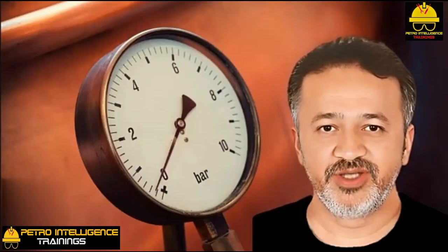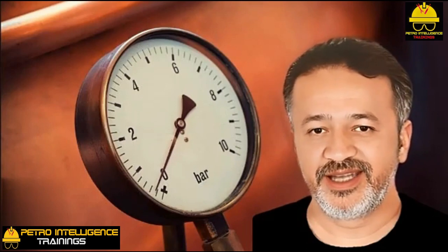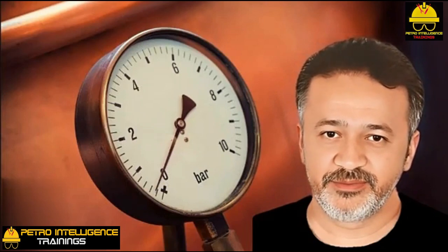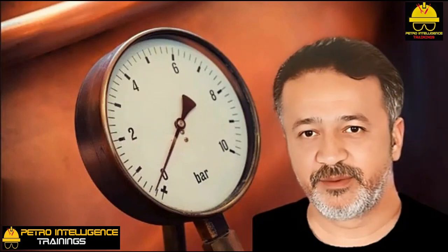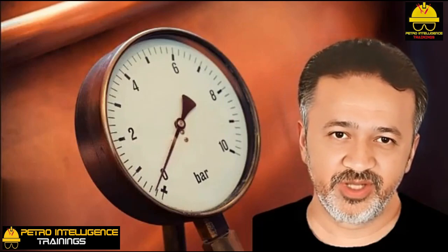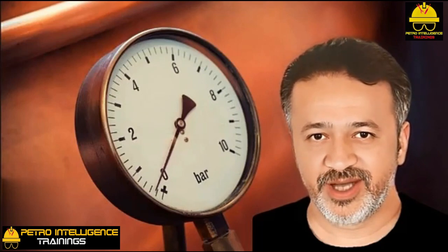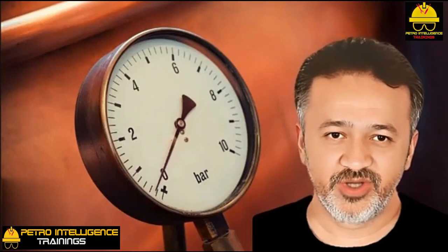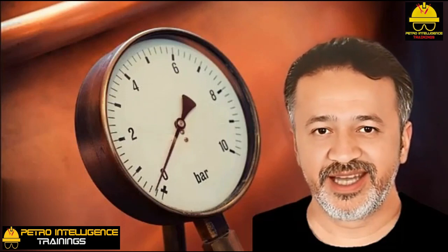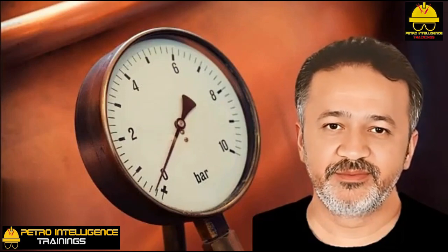Pressure point location. Locating a pressure tap in an area of high velocity is likely to produce a lower pressure indication than the real flowing pressure. Using a purge gas to keep a pressure tap from plugging often can cause a high pressure reading if too much purge gas or steam is used. A pressure tap located below a liquid level will read too high. Pressure should be measured in the vapor phase. A pressure tap opposite an inlet nozzle with a high velocity will read higher than the real pressure.